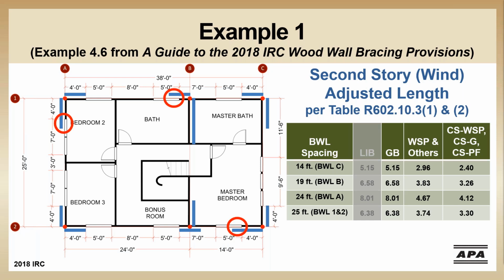We've got circled here. Now, because our goal is to get all of the loads down into the foundations, we're not going to worry about openings in the story above our braced wall panels, but openings in the level below our braced wall panels are a different story. So these won't be a big deal for wind design, but they could trigger a seismic irregularity, so we need to revisit this a little bit later.